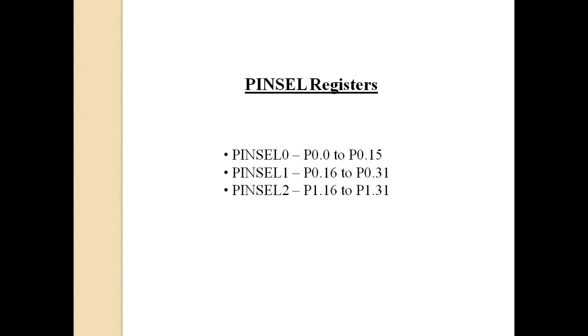Similarly, for configuring a GPIO, you are having a set of special function registers or SFRs. First set of register is known as pin sel register. These registers are used for configuring the functionality of each pin, because each pin is having more than one functionality.